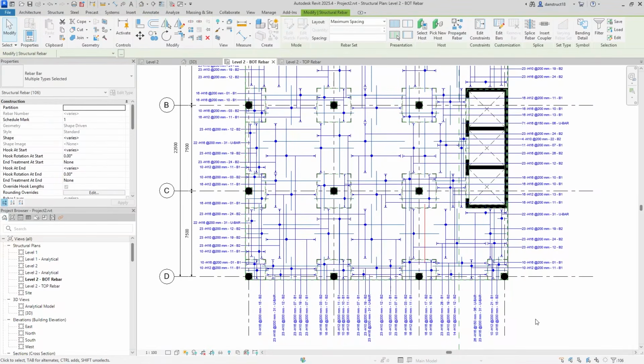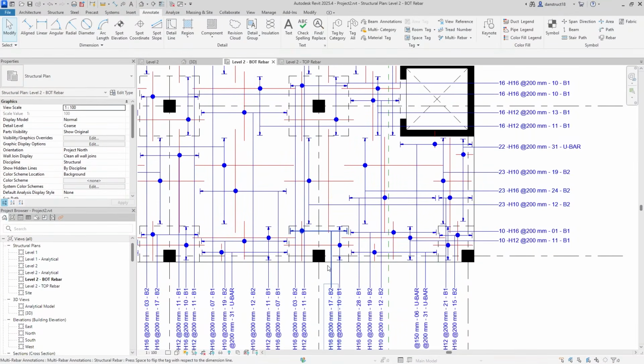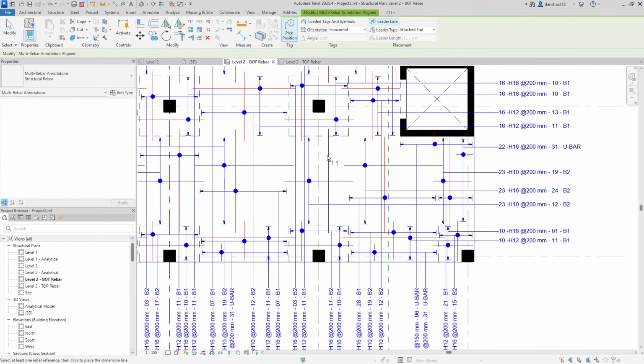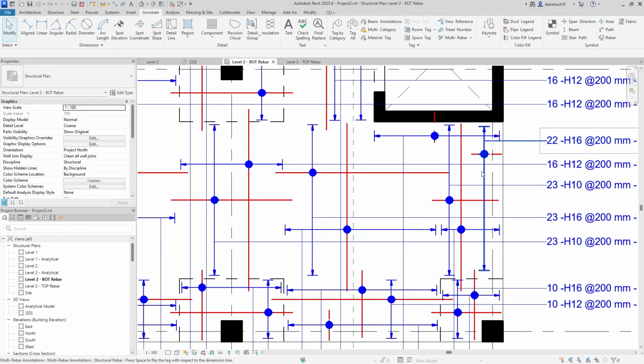So this little one here, we're just going to target, and if I don't find the room downwards here, I can just click on Rebar and I can target to the side. See, we have lots of room on the side. So not too much, but still enough. So I'll click here, and I'll place in this direction. Once I'm done, I'll press escape.